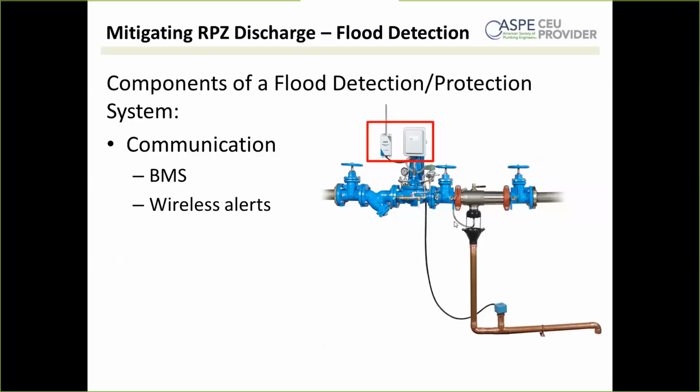So I won't worry too much about it, but that being said, having straight lengths of piping is great because it makes the backflow preventer operate a little easier, because you're going to introduce less chaotic flow to the suction and discharge side. I'm going to have to look up to see if we have specific recommendations, but like I said, because we do have those N and Z type backflow preventers, it's not a huge consideration the way it might be for, say, a pump.